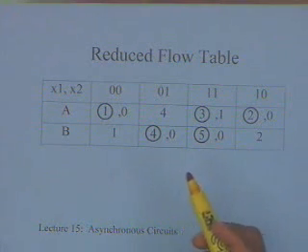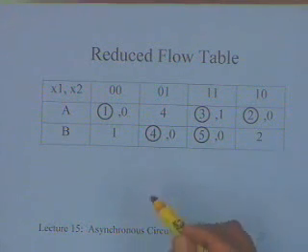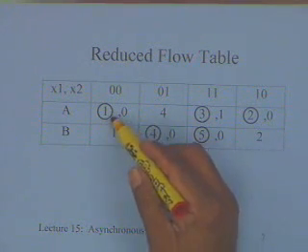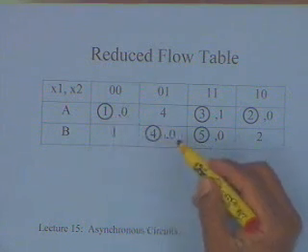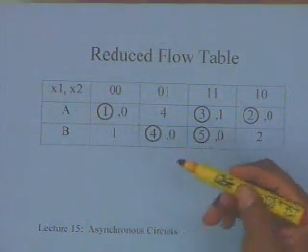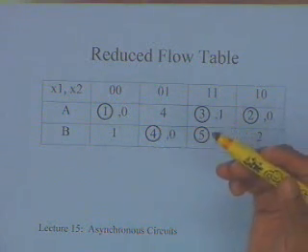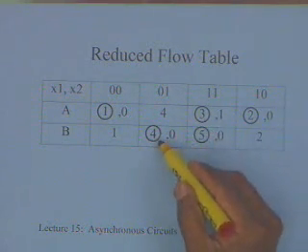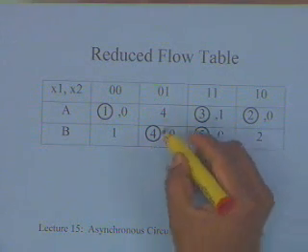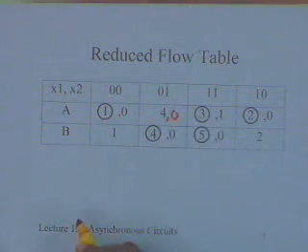There are many ways of assigning it. Sometimes people assign starting from what the output was before, but the strategy that we can follow is we will try to make the outputs as early as possible. We will try to reach the output. That means I will associate the output that is there with the stable state, and I will associate an output of 0.